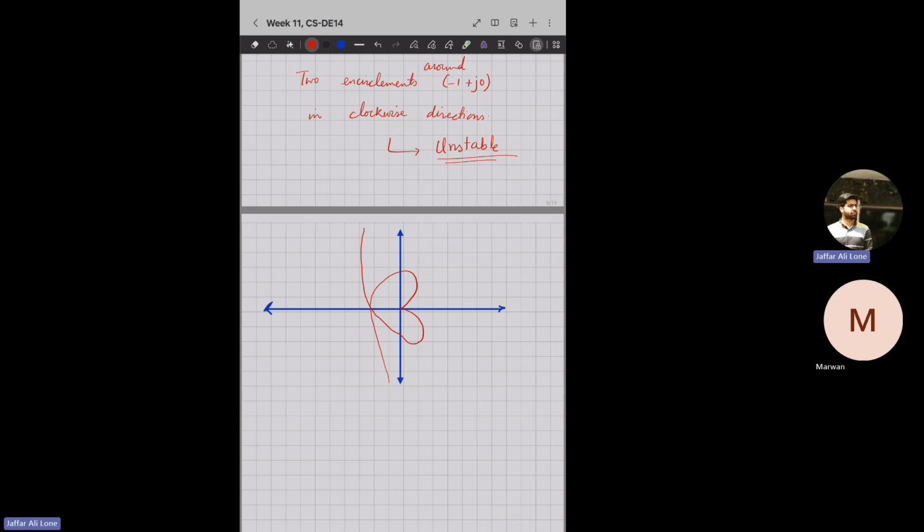So then I have type 1, and there is one semicircle of infinite radius, right? And your minus 1 comma 0 point, which is actually given after a lot of calculation, it will be somewhere here. So you see there are two encirclements in the clockwise direction. You see this -1, 0, it's encircled. One is this, and the other one is this.